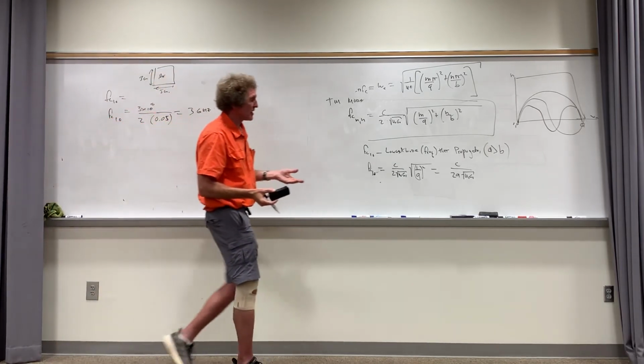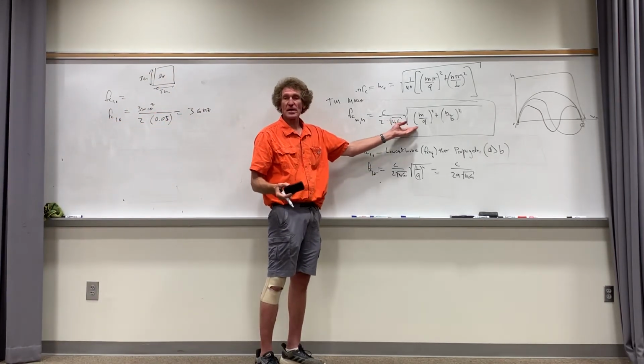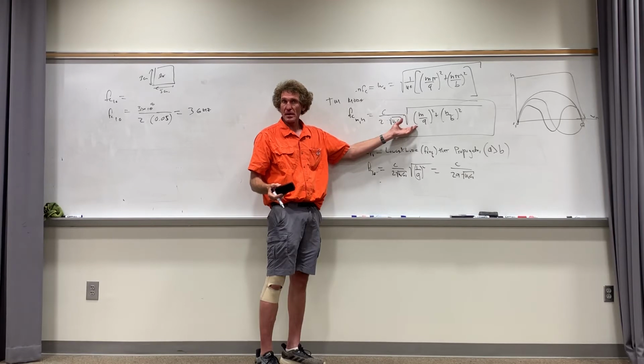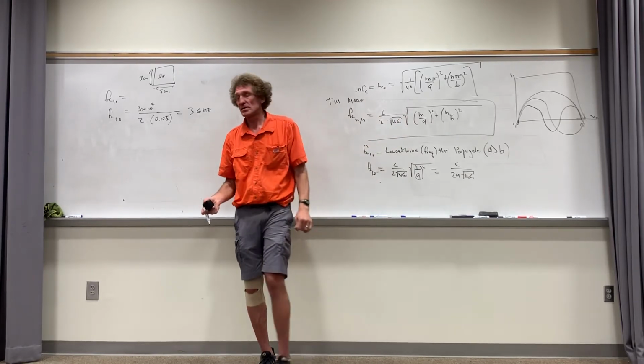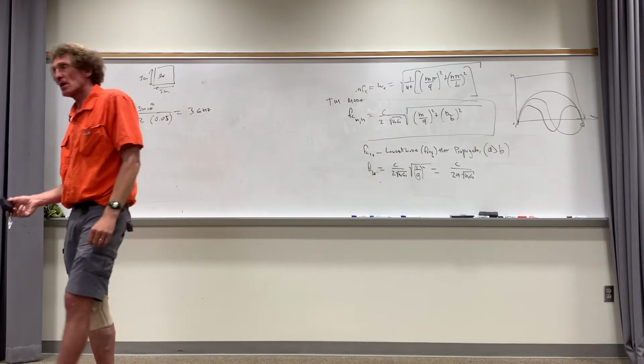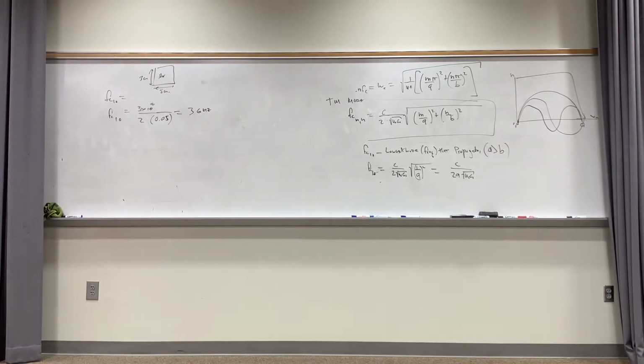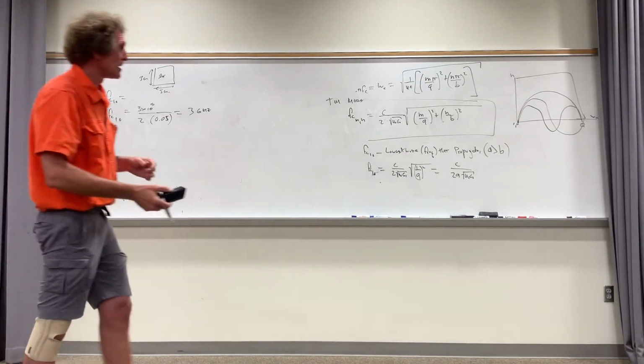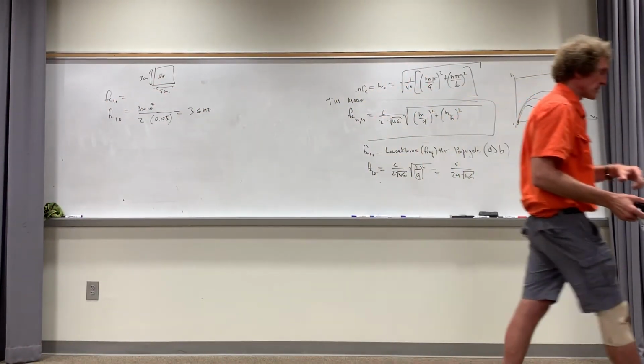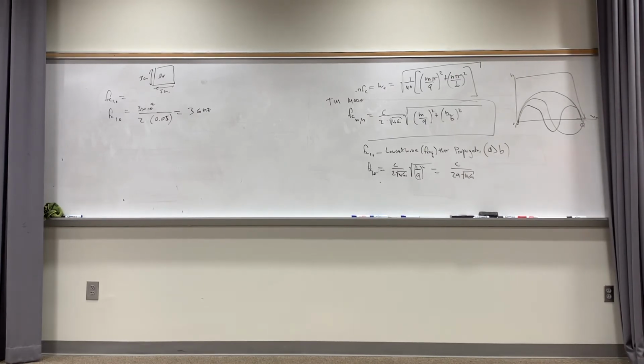You could also calculate the cutoff frequencies for any mode, couldn't you, class? You could calculate the 1,1, the 2,1, and all that. Those are the cutoff frequencies. Now, to get the electric and magnetic fields in the other directions, if you look in your book for a second, I don't think I'll have time to do all this, but we have EZ, correct? And if you take a look at your book, I'm not sure of the page, but I'll tell you in a second.